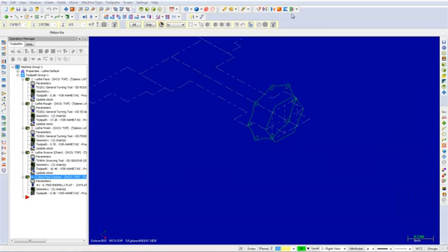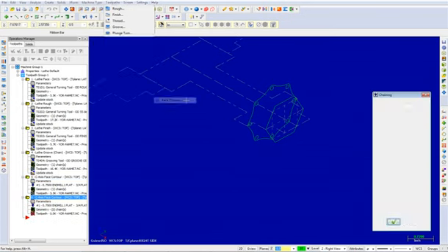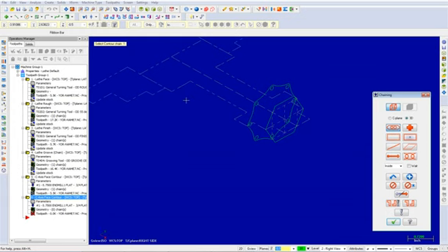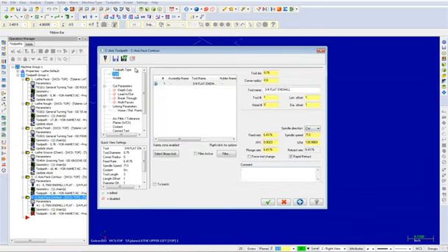Once again, select Toolpaths, C-Axis, Face Contour. When the chaining dialog box appears, select the larger polygon we created and pick the OK button. The C-Axis Toolpath dialog box will open. From the Tree View list, choose Tool. Now input the comment as shown below.